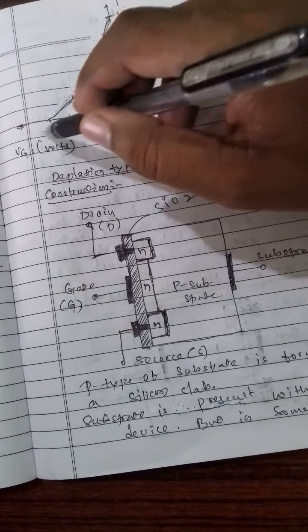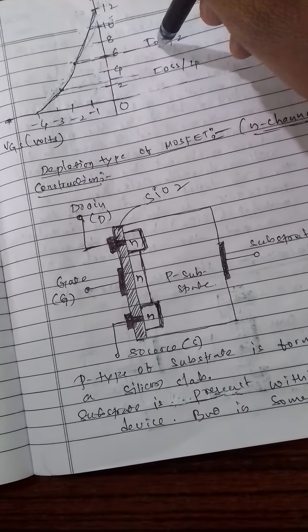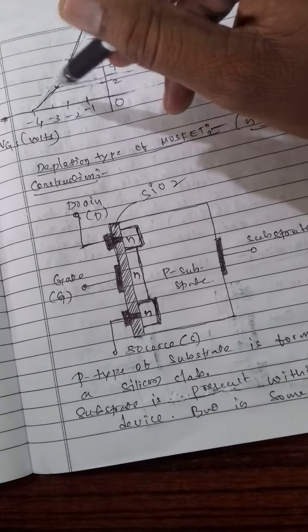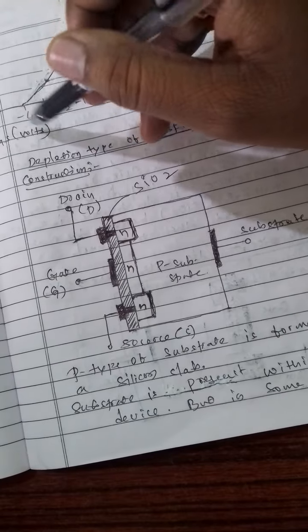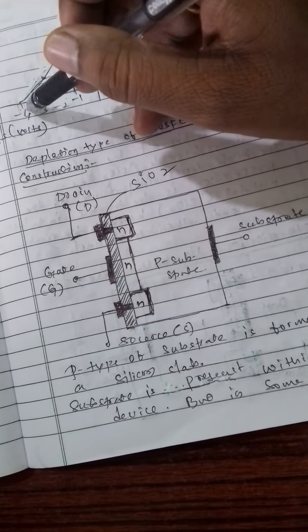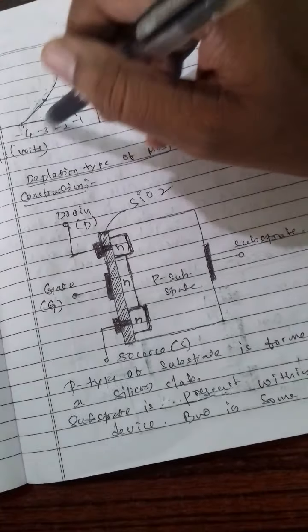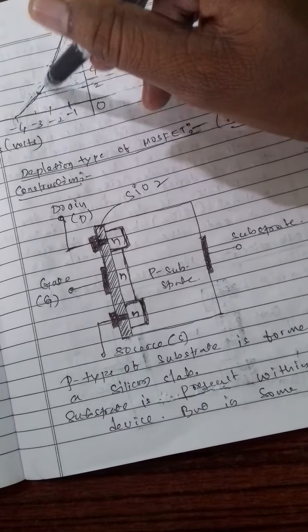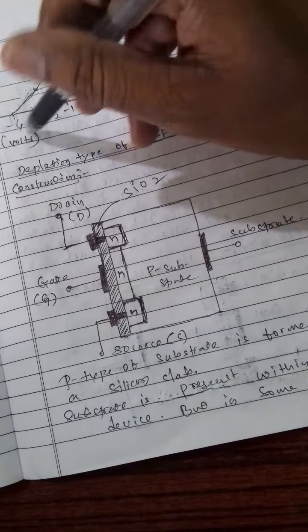for the given JFET, so that here IDSS upon 2 and here it is the VGS, and here IDSS upon 4 and here it is the VGS. If we join all these parameters, here VGS is equal to pinch off voltage VP, and here ID is equal to IDSS at this point. So from these equations, if we get these points and join all these points in the second quadrant, you will be getting the transfer curve for the given JFET.